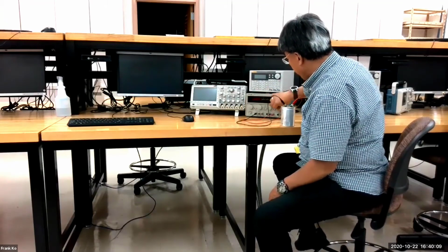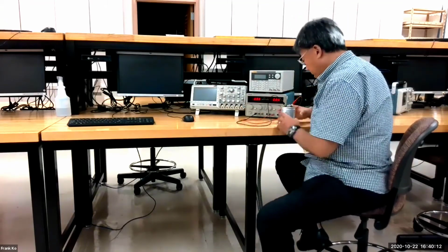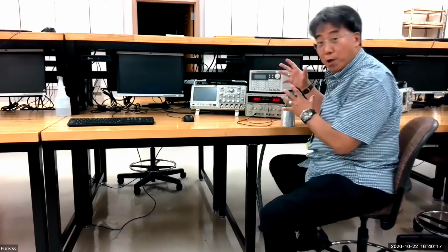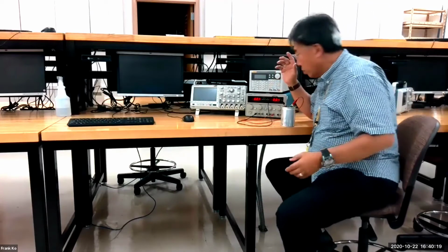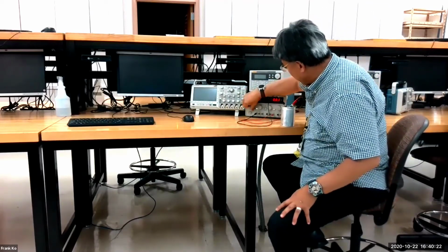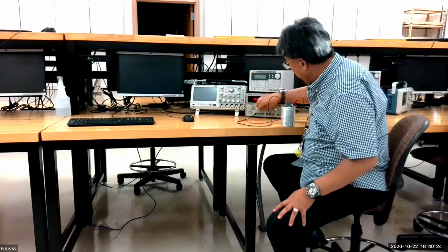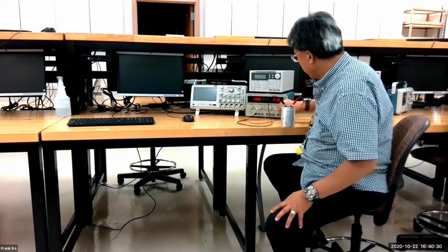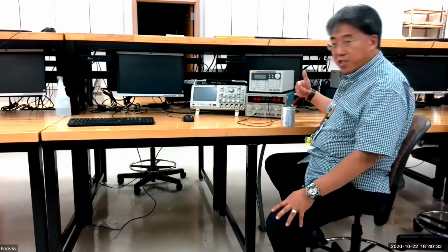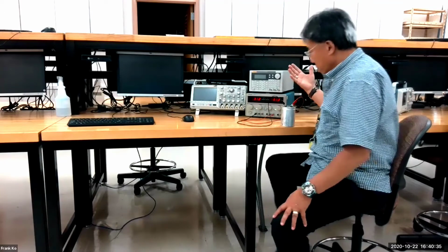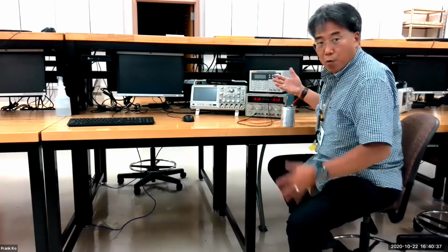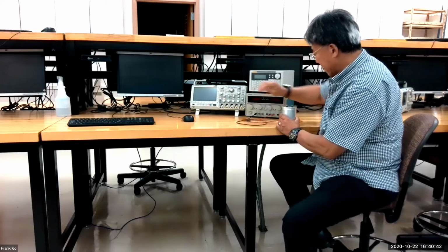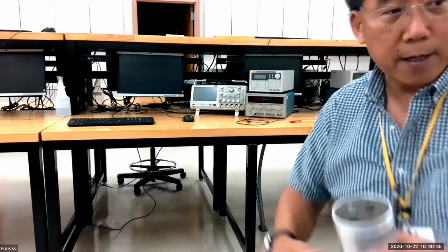Turn down the current, turn down the voltage, turn this puppy on, double check my polarities: positive, negative, positive, negative. I don't want to blow it up while I'm demonstrating. That really would not be cool. Turn up my current. And now turn up the voltage. I got 30 and 30. I've got 60 volts on this right now. It doesn't need any more time to charge than this. Turn this guy off. This guy is fully charged. Disconnect. So it charges up pretty quick.